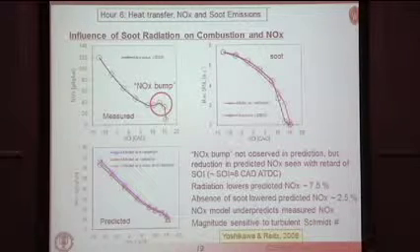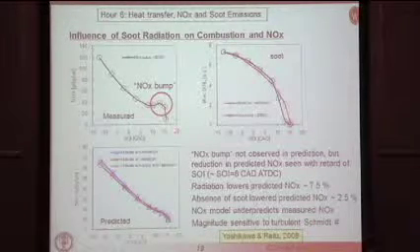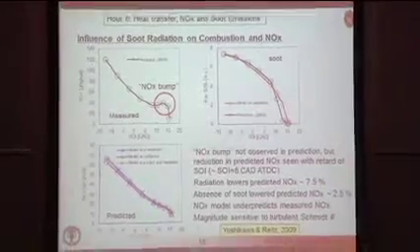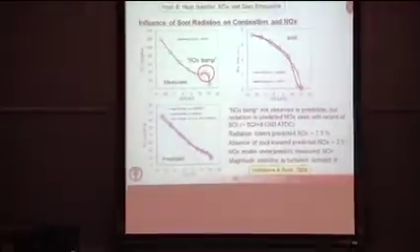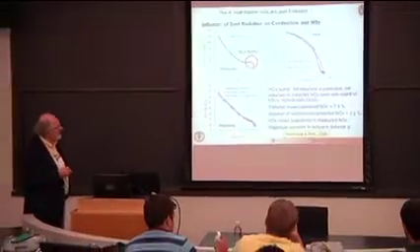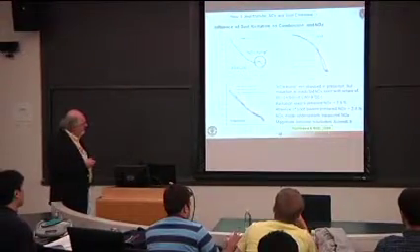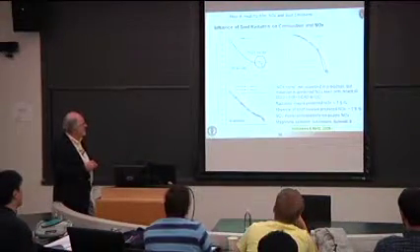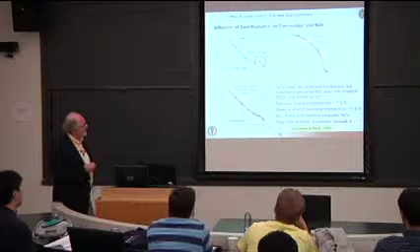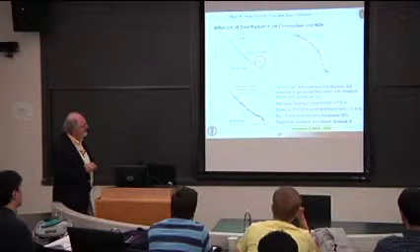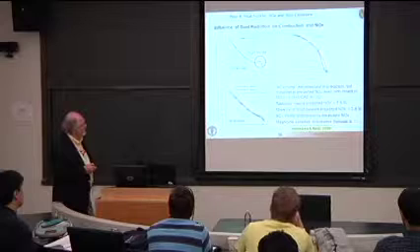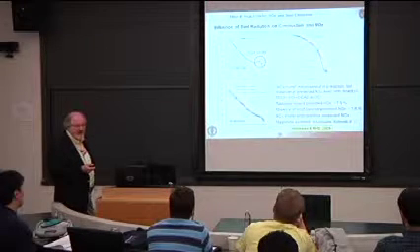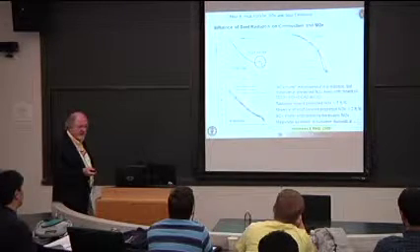So this is Mark's measured data for those different start of injection timings. As he retarded the injection, the NOx decreased, and then he saw this interesting bump here. And he argued that the reason for this bump is that if you look at the measured soot data, around this start of injection timing, you suddenly see a big drop in soot.